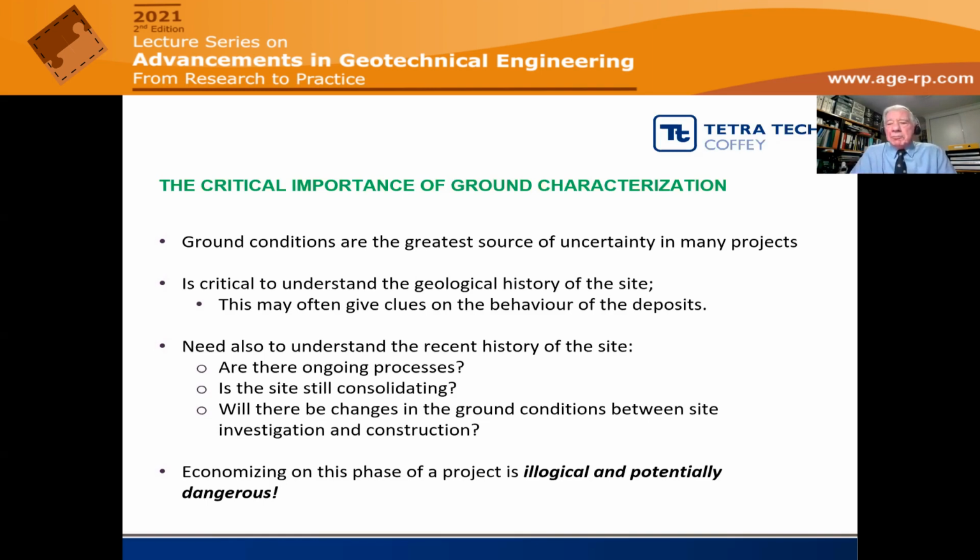There may be ongoing processes. The site may have been subjected to filling or reclamation some years ago, and that may still be happening, that the consolidation due to that previous process may still be happening.